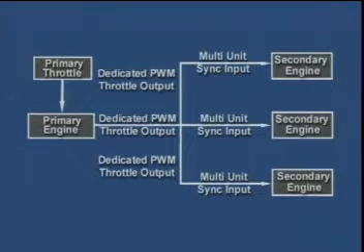The soft-coupled marine application sends the throttle signal out to all the secondary engines through the J1939 data link. Since these engines are wired in parallel, if one engine stops, the others remain running. The ID pins configure each engine to operate either as the primary engine or one of 5 secondary engines. By using the pins, the need for a separate calibration for each engine is eliminated. In addition, for a service tool to communicate over the J1939 bus, it must be able to recognize which engine the information that it currently is receiving applies to.